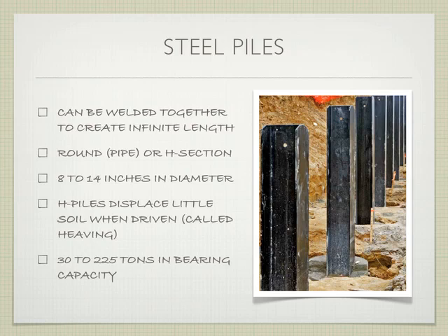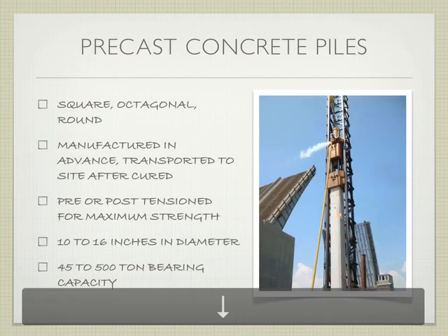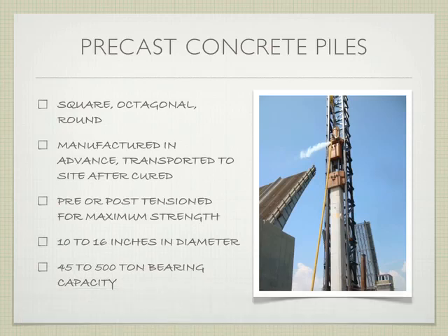If we were going to drive piles for the New Bay Bridge, would we want to use steel? Probably not. Same issues. So steel's great in a place where it's not in contact with things that cause it to corrode. So what have we come up with to combat that? We come up with precast concrete piles.